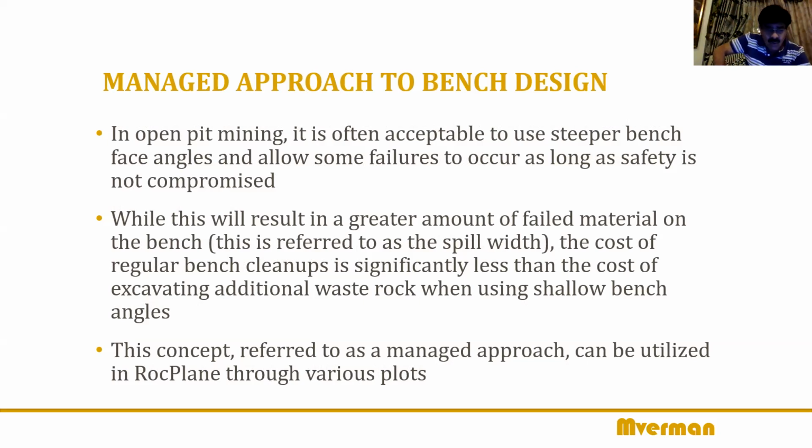You know, there's a place called Goa in India. I'm sure most of you know about it. Goa is a typical place which is also very rich in minerals. There are lots of iron ore mines in Goa, and Goa is a place where tourists go and it's a habitated place. It's one of those rare examples where you have open cast mines in the middle of habitation. And they have a typical problem. They can't go wider than a certain angle or certain width at the face.